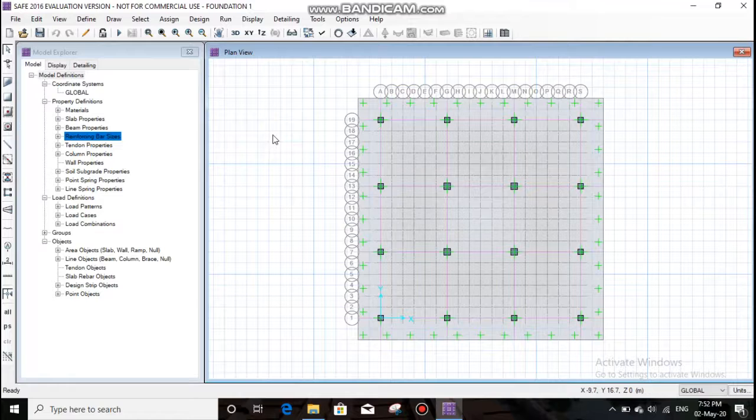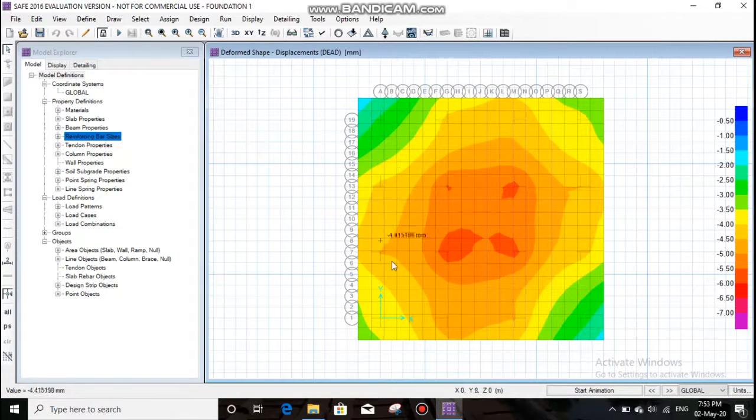After assigning the load values to individual columns, and after assigning the properties and checking whether the strip and the load are assigned, and whether the rebar material is HYSD for all the elements, we will now run the analysis. Run analysis option. The analysis results will be shown.